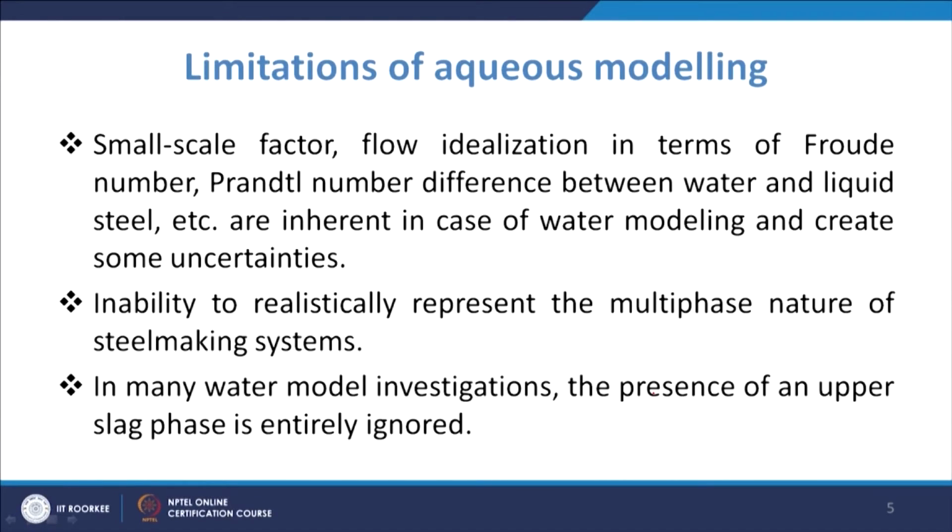In many water model investigations, the presence of an upper slag phase is entirely ignored. So, what we do normally is ignore this slag level. When we do the physical modeling, these results are used to validate first, and then we try to have the results from the numerical investigation.